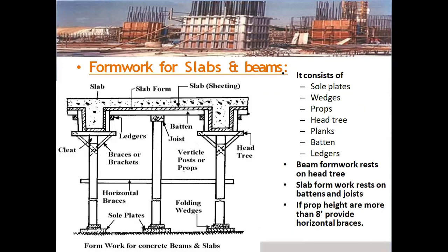Formwork for slabs and beams. It consists of sole plates, wedges, props, head tree, planks, batten, ledgers. Here, the beam formwork rests on head tree.